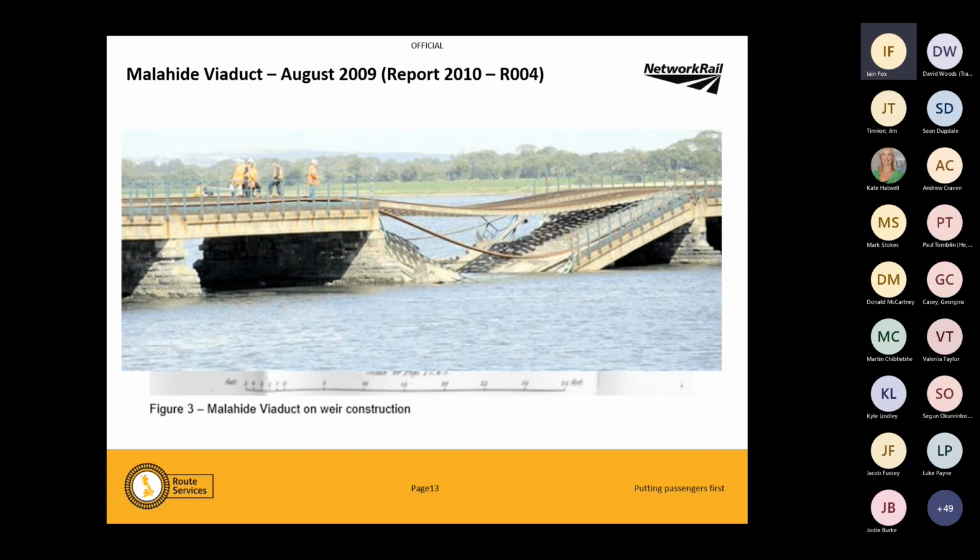That is the historic drawing of that viaduct. So thinking of the things that we spoke about earlier on, Q equals VA, so flow rate equals velocity times area. So we've got a nice big depth open channel coming in. We go through the viaduct over this mound, and we go back. What have we done here? We've reduced the area that water's got to flow through. We reduced the area, we've increased the velocity. So the velocity of the water going through that weir is phenomenal, and that's caused that to happen.